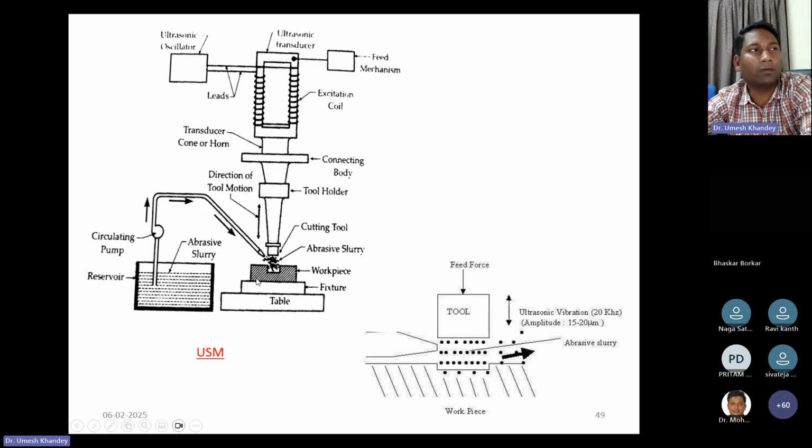Ultrasonic machining will also be there with you in the machining center. There the ultrasonic frequency is going to make contact with the abrasive slurry, which is going to erode material from the workpiece. The abrasive slurry performs the actual cutting, and it is pumped near the zone, in between the horn and workpiece, to remove the material. The abrasive slurry is going to give you the same shape as the horn you have as a tool. There will be many mechanical arrangements to ultimately accomplish the removal through the ultrasonic principle.